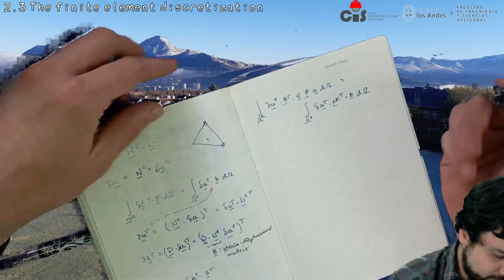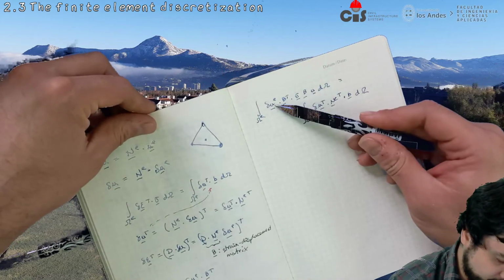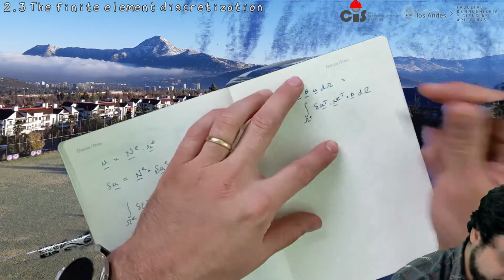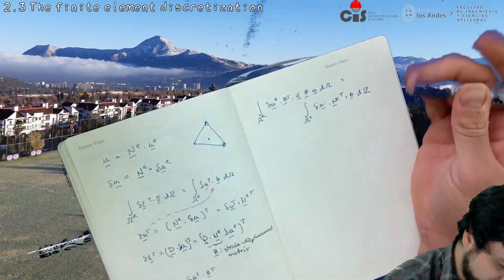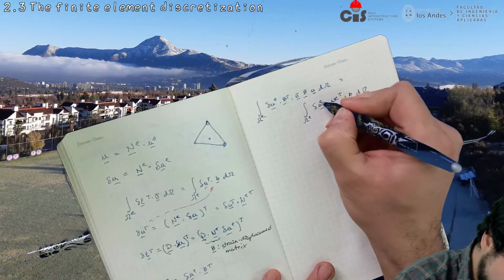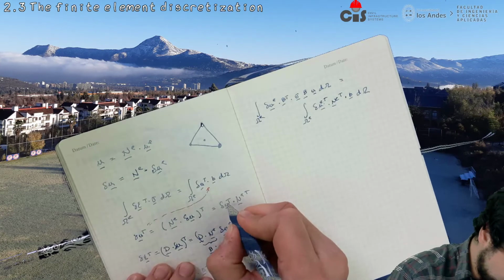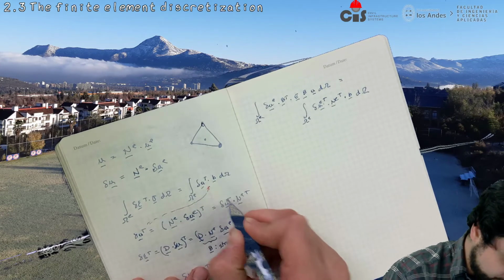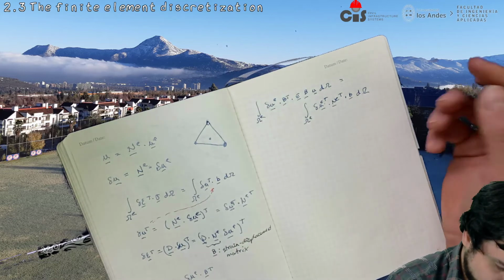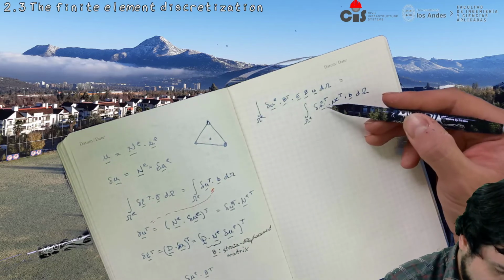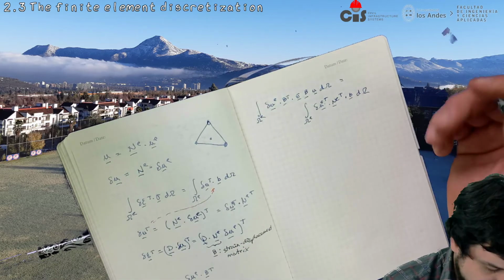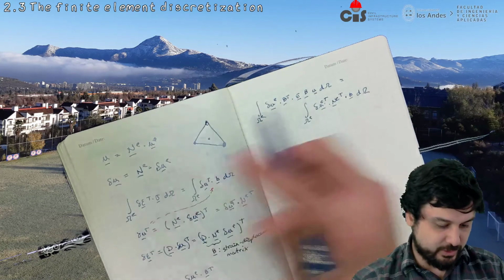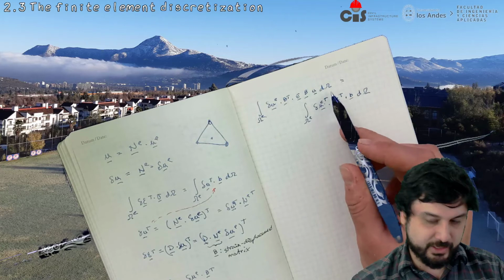And right now, these UEs that are listed in there, this one is also UE transpose, and this came from here, so this is UE. These ones are values at the nodes, so they don't depend on where you are inside the domain. They're not a function of whatever xy coordinates you have.